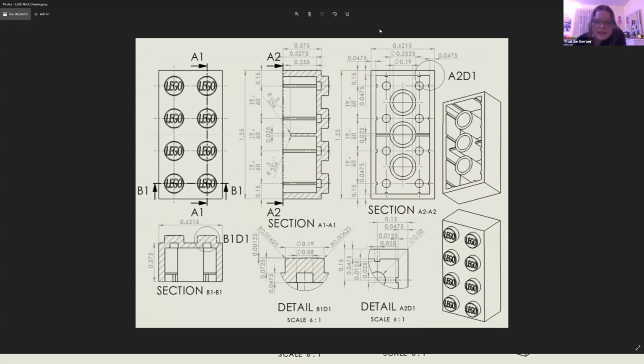And then what was that distance? What should I do for distance in between each one? Because I'm looking at the drawing, I can't quite find it. With the linear pattern, the distance we specify is going to be the distance from the center of that body to the next body's center. So in this drawing file, do you see this section V in the center? Hold on. All right, yeah.